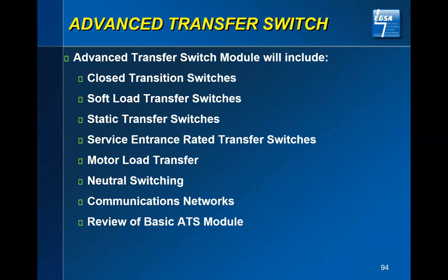If you're putting this transfer switch ahead of that distribution board, now the first device the utility hits is our service entrance rated transfer switch. Now we are responsible for providing that circuit breaker. So it's sort of a two-compartment unit, the transfer switch along with the circuit breaker.